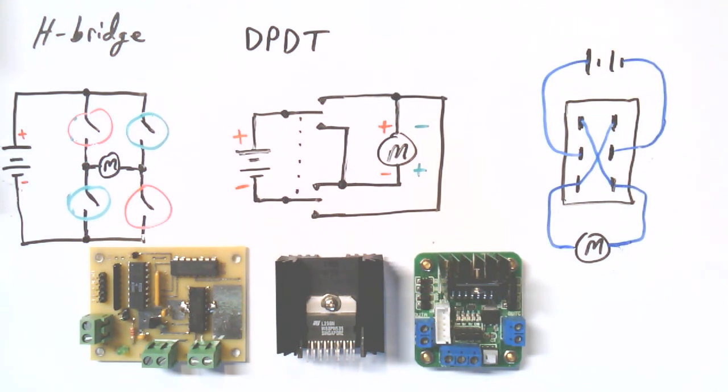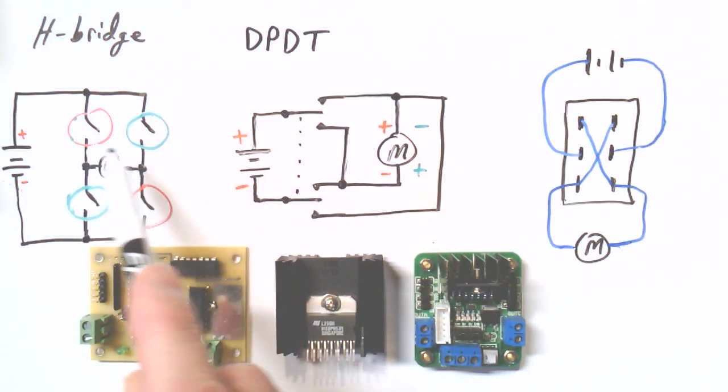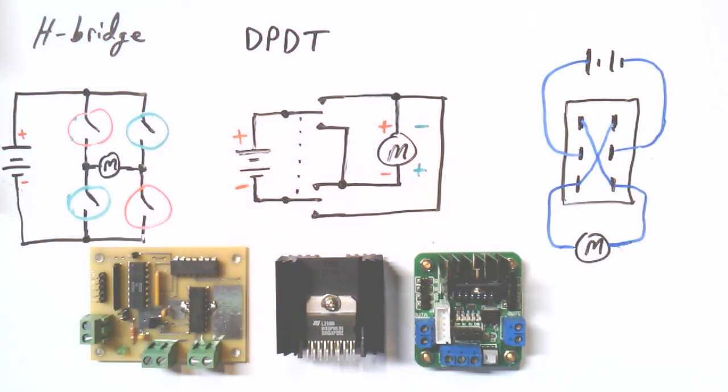And speaking of transistors, I do have some examples here of what a circuit that employs an H-bridge might look like if it's all solid state. I mean, it's definitely true, you can have discrete transistors. You can have power transistors sitting here. That's possible. These examples I have are a little bit more on the smaller side. This is, let's see, what is this? The L298 is a pretty common IC. It's a dual H-bridge. Then it also has other features.